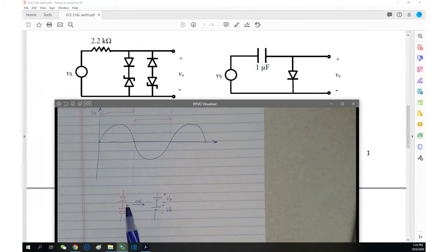However, be very careful. The zener here, the model of it is what? Because this is reverse bias, reverse the bias. And then this VZ is what? It is the breakdown voltage, not the forward cut-in voltage. That's why the polarity is opposite to that of the diode. Did I make myself clear here?